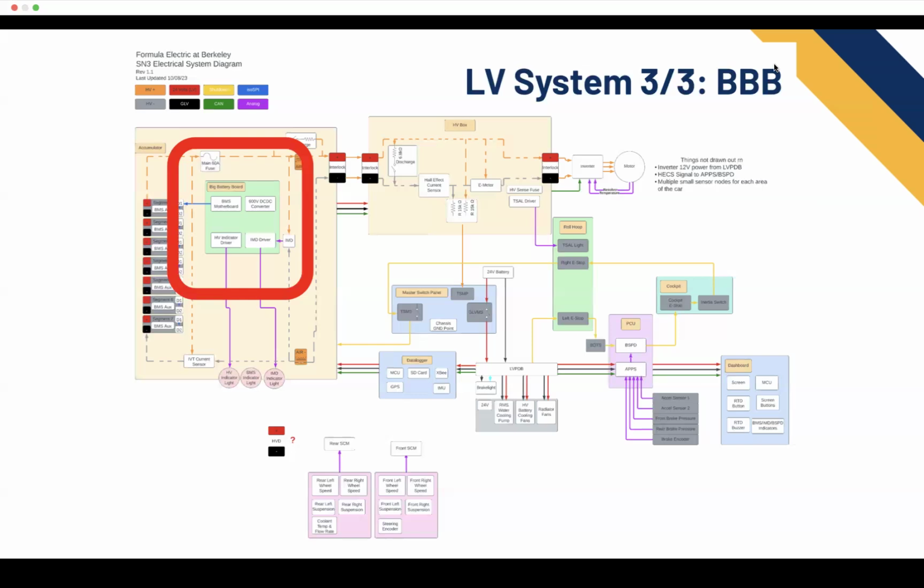Also, the IMD driver is on this board. The IMD driver just drives the indicator light. The IMD, or the isolation monitoring device, is its own PCB that we're required to buy as per competition. Every team has the same one, and you have to buy it. So that one you can't make custom, but we can go over isolation in a different lecture. I also explained it to a lot of you during recruitment, so hopefully you have some idea from there.